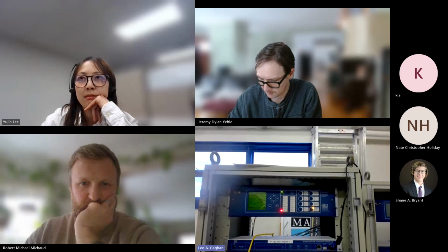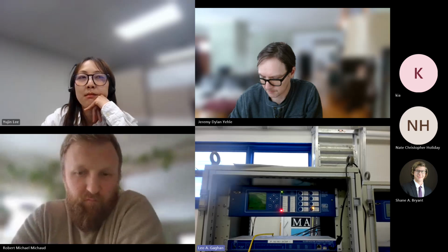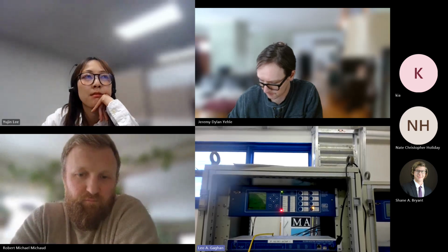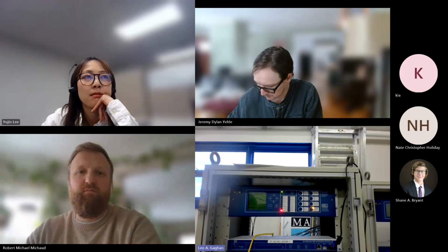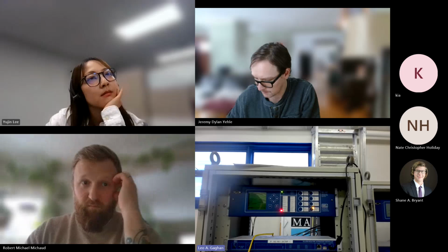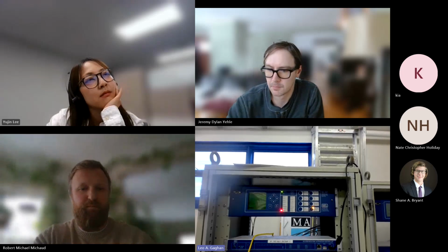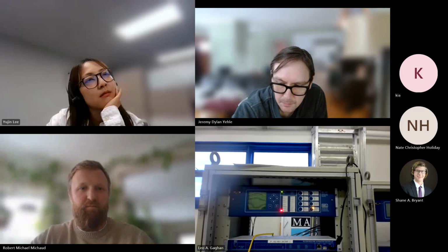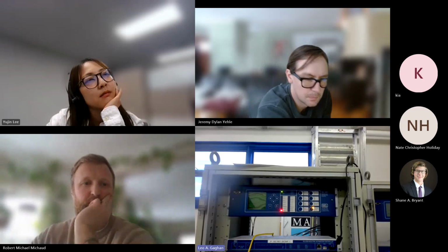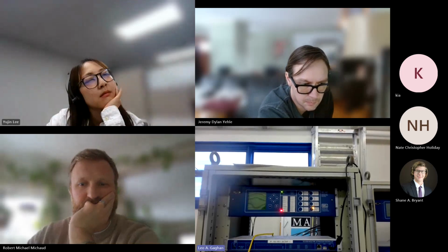And it's because of that NOT gate, right? Let's say that was off and that was a 0, well, you have a 0 right here. Come around, you have a 0 going through a NOT gate, that's a 1. And then you have this signal come in. Well, a 1 and a 1 going through an AND gate will set it. And then once it's set, now you have a 1 over here. Well, coming back this way, a 1 going through a NOT gate is a 0, so we can't set it anymore. But a 1 with a 1 resets it. Little toggle. If you want to get real clever, try and wrap your head around that one. It's so simple, but